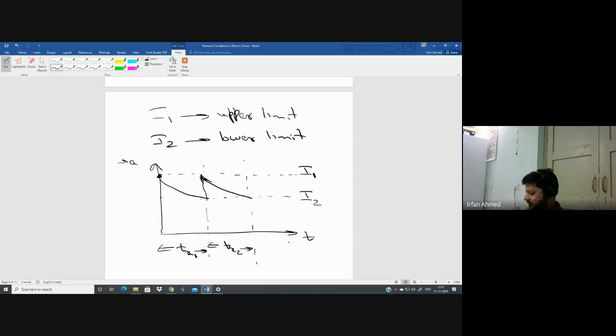I'll think about it and tell you later. But you will never have your starting current that low, because too much resistance will be required. Starting efficiency will be poor. Starting time will be increased. There is no such thing as black and white. If you improve one thing, the other thing regresses. If you improve the other thing, the first thing regresses. So it is all about compromise, choosing the optimum point, optimal values.